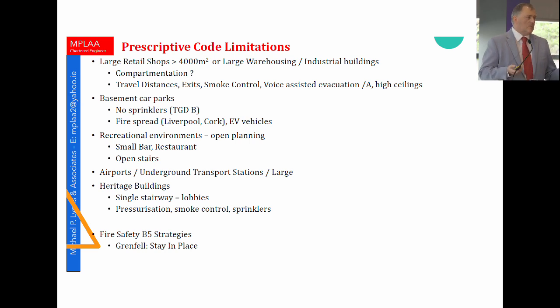And then behind all of that, don't forget, there are assumptions in relation to our fire safety strategies. Like the Grenfell Tower fire, at the time when it occurred, the British strategy was that of stay in place. So everybody who rang the fire brigade were told just to stay in their apartment. The fire brigade will come, will rescue you, and you'll be taken out safely. Well, the strategy in Ireland isn't that. Strategy in Ireland, by and large, is fire alarm activates, you leave the building.